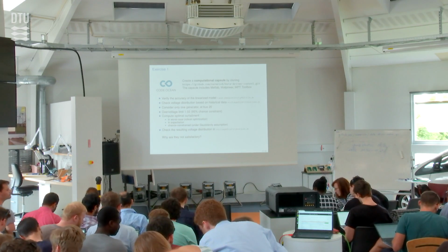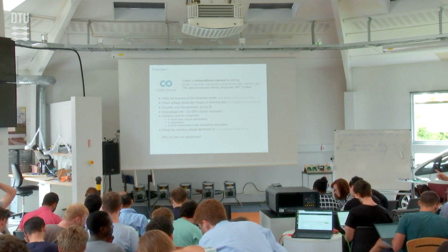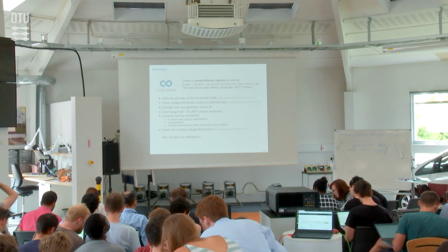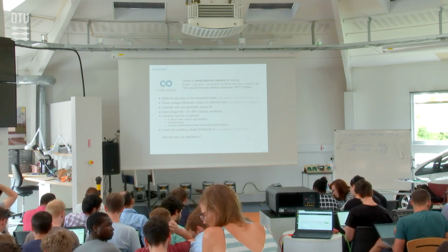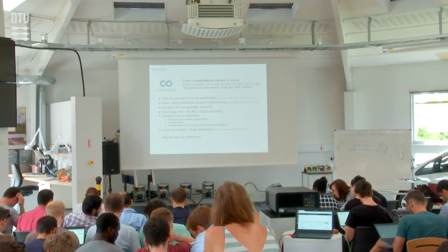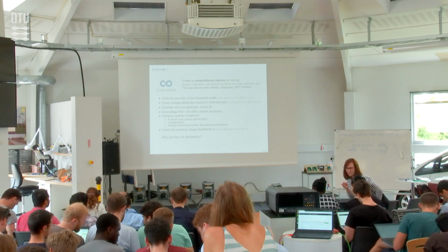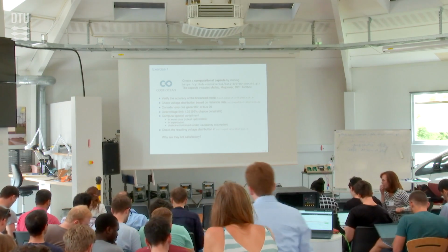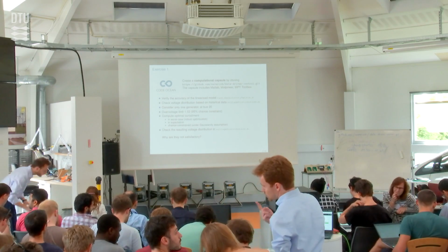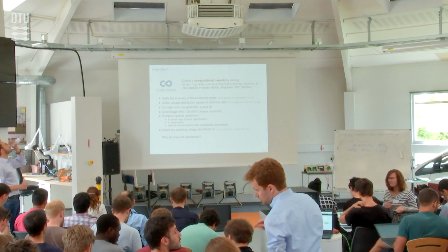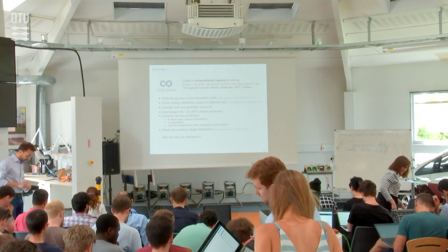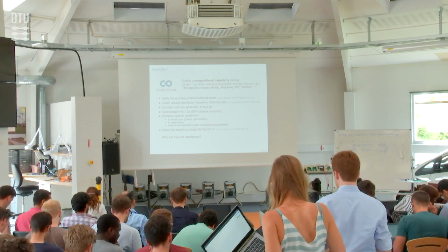Okay, try. Do I press this? No, you have to press on this one. There is an arrow on the right. Yeah, that one, and say set as file to run. And then it runs. But this is only for now. Later you'll have your own script, exercise1.m. You set that one to run, and then you do everything there. You don't have to change it anymore.